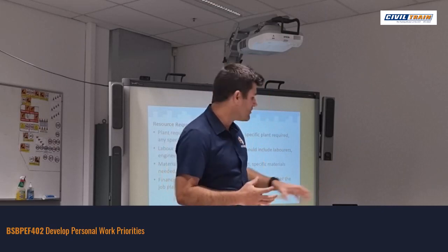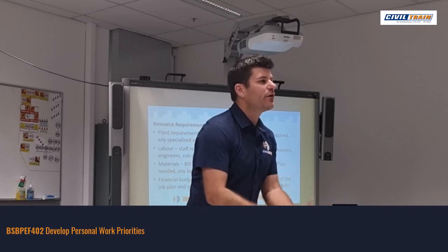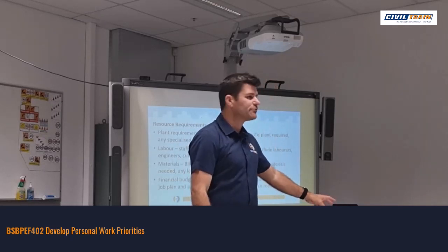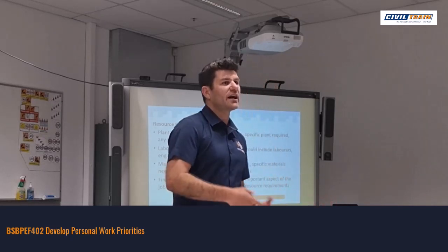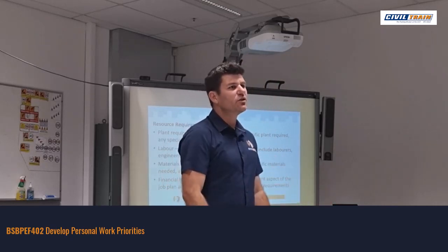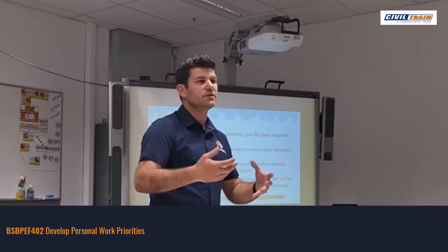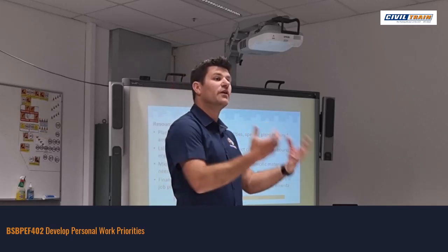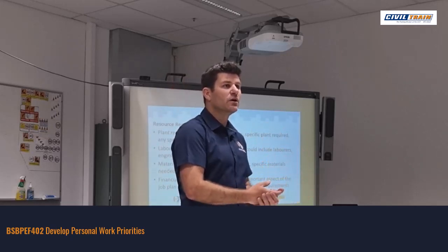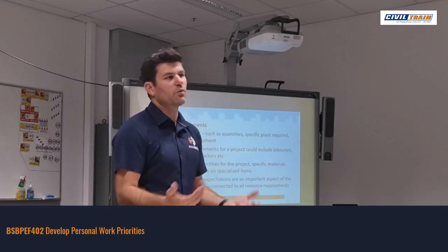One thing I'm looking for realistically though, is when we're planning it, if you've got your concrete pour happening on day 5, and on your key resource delivery, you've got your concrete coming on day 6, obviously I would see a discrepancy in your plan. So all you're really showing me is you understand the process of planning that, if we're going to do site setup, you would expect to see your fencing and resources arrive on the day or the day before, not 2 or 3 days later. So it's just you guys showing me you understand when you would want those resources.